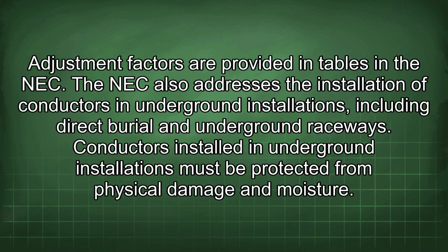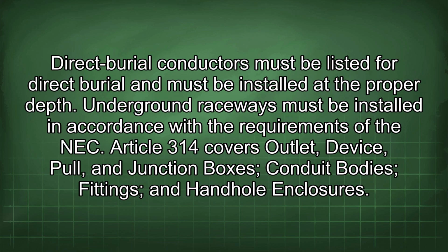The NEC also addresses the installation of conductors in underground installations, including direct burial and underground raceways. Conductors installed in underground installations must be protected from physical damage and moisture. Direct burial conductors must be listed for direct burial and must be installed at the proper depth. Underground raceways must be installed in accordance with the requirements of the NEC.